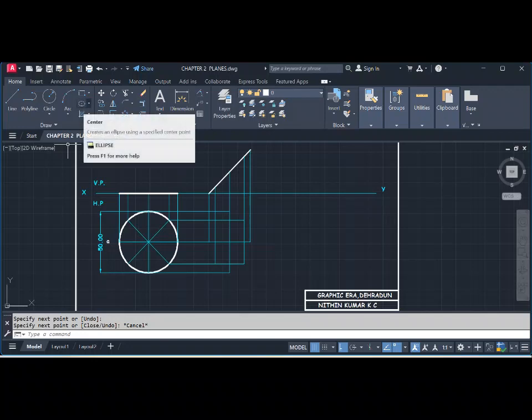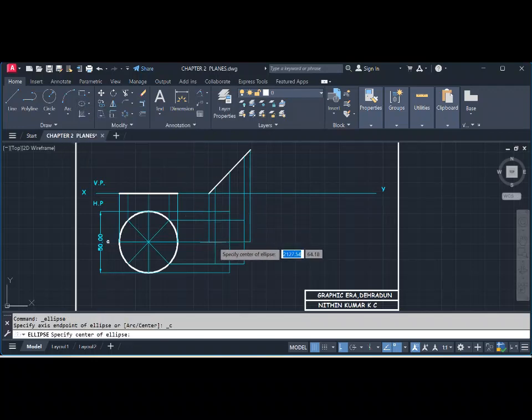So once you're done with this, you take the very beginning ellipse, center ellipse. So center, semi major axis and semi minor axis. Again you see in this particular ellipse, it is also a curvy surface. So for the further projection step, this line will be inclined to VP at this one. This is the resting point. This is the diagonal passing through this. This is inclined at 50 degrees to VP.